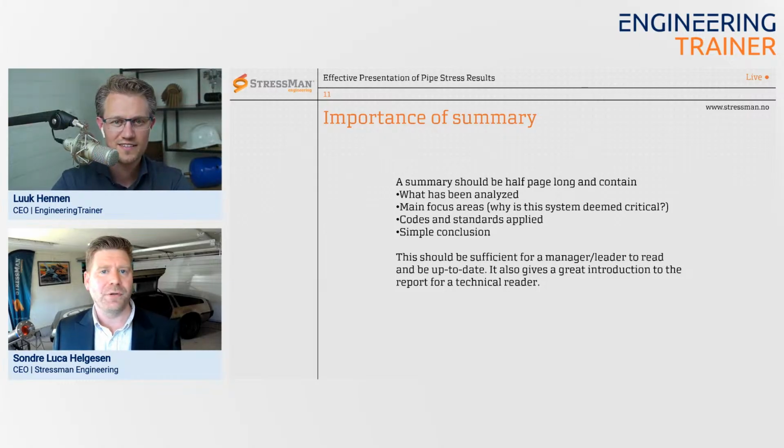If you don't know any better, you can assume some factors, and you know you are conservative. Then if you're having a problem getting compliance, you can start digging into setting up a detailed FEA, for example, to verify that your real factor is lower than the factor that you chose.